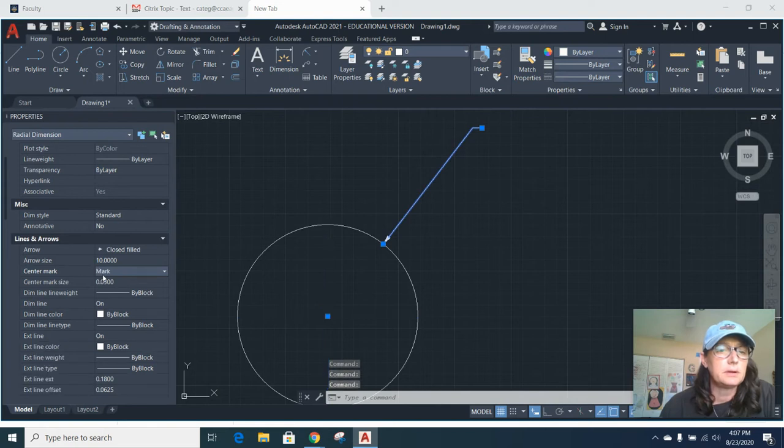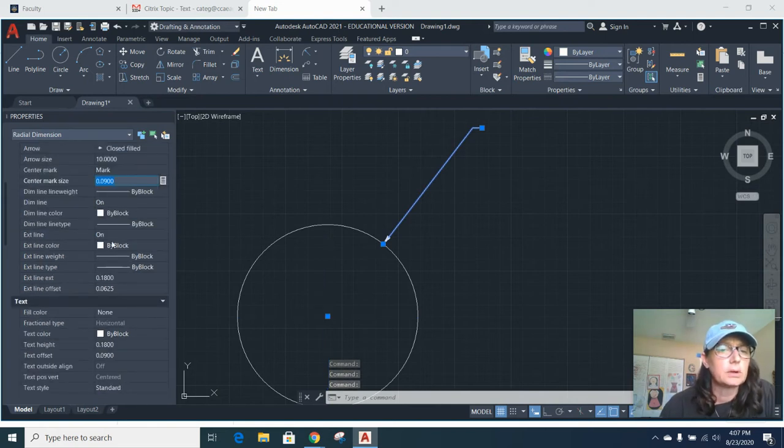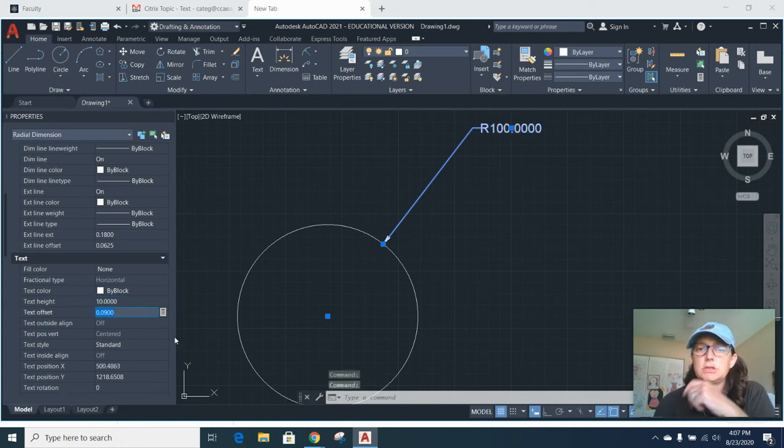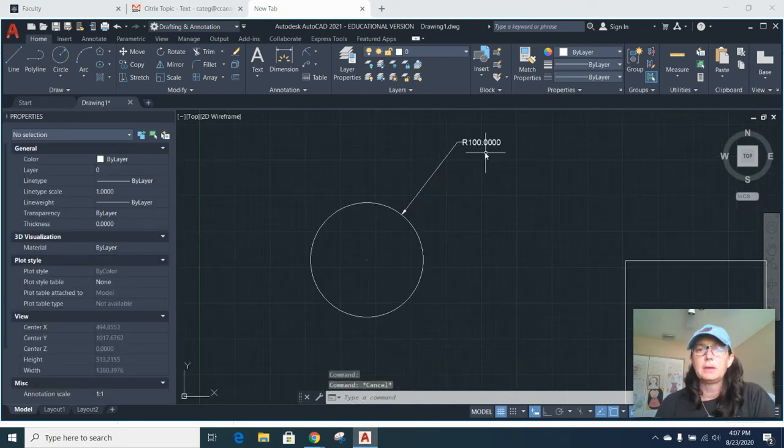The next thing I want you to realize about is your height. You can manipulate it and make it prettier or aligned with certain elements of the dimension line, but right now I'm just going to focus on what you're utilizing to indicate where you're pulling the dimension and the height of the text so it's visible. So again, maybe we put 10 in there too, because we already know that the arrow is very apparent at 10 with this size. Okay, so if you escape, it is now unselected. Okay, so I have the radius of this circle. So I used the radius.